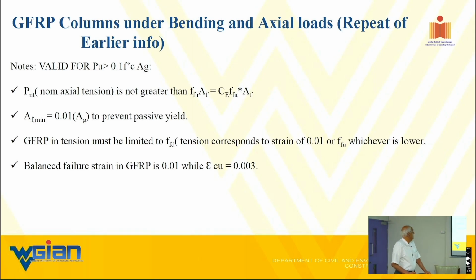Okay. So I already told you that 10% thing. If your PU is not exceeding that 10%, then you don't have to worry. The design comes into play only when PU exceeds 10% of your concrete stress times the area, which is the force.